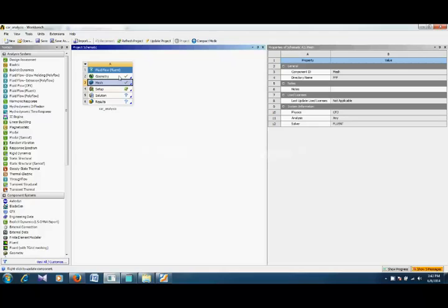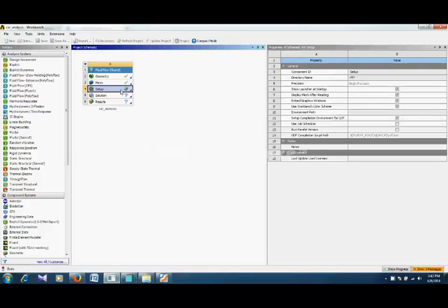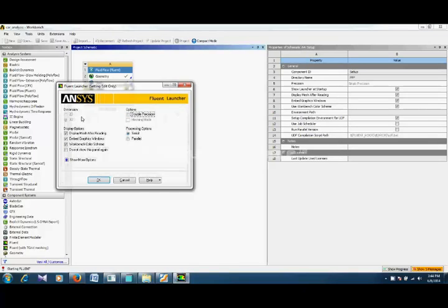Now we are done with our design modeler and meshing. Now we set up our solution. Here you can see that our dimension is 3D and it's blacked out because now you cannot change it from 3D to 2D, so you must select your analysis type at the start. This double precision means that it will go up to 16 digits after the decimal point, and it will obviously take more time, so we keep it single precision. It means that if double precision is unchecked, it is single precision and it is up to 8 decimal points.